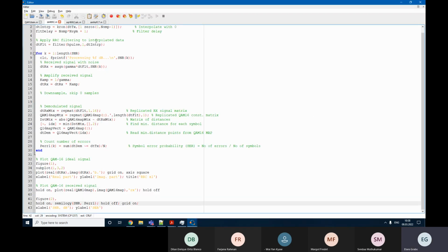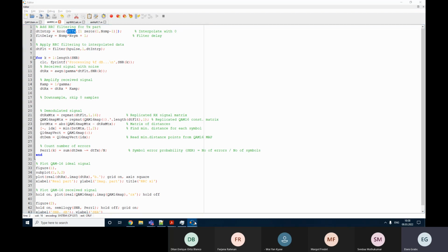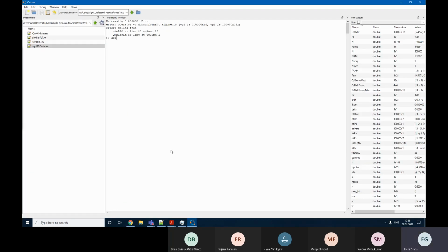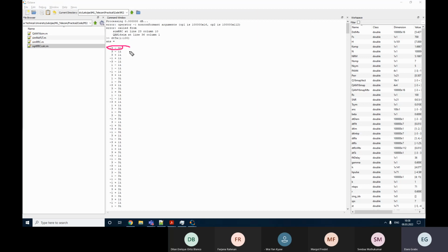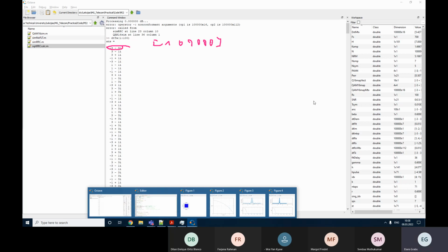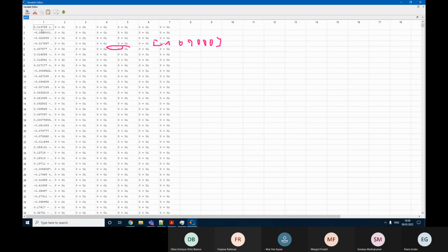So here, when I was upsampling it with zeros, data transmitted wasn't a row, right? The first 100 values are a column, and it did exactly what I asked. It replaced this value with an entire row of 1 and zeros multiplied by this value. So if I look at data filtered, we have value, we have zeros.